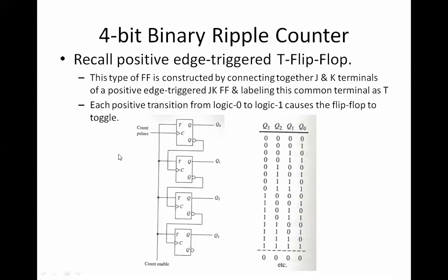Instead of representing it in the horizontal fashion, we are representing it in the vertical fashion. And the clock pulse is initially given only to the first flip-flop, and the rest of the clocks depend on the Q bar output. This kind of representation, where the clock is enabled by the complemented output of the previous flip-flop, is called asynchronous. Keep in mind, it is asynchronous.